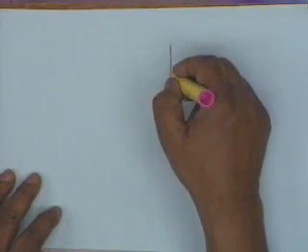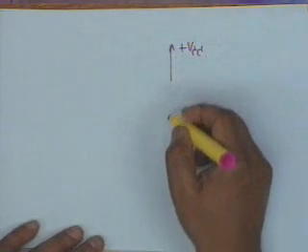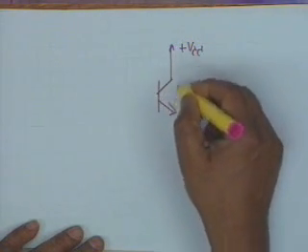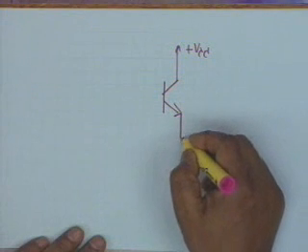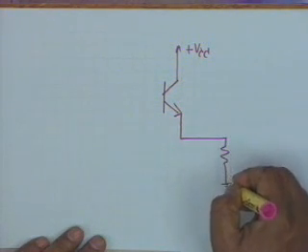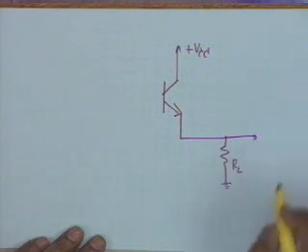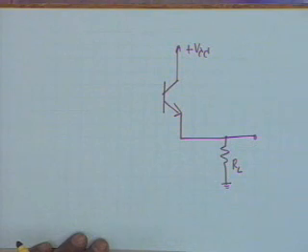Now, let us look at the power amplifier, transformerless power amplifier using complementary transistors. The total circuit is known as complementary symmetry circuit. Now, try to draw with me. We have plus VCC. Let us draw the NPN transistor first. You see there is nothing in the collector because it is to be an emitter follower, and the emitter is then connected to an RL as you saw earlier and the output is taken here, alright.